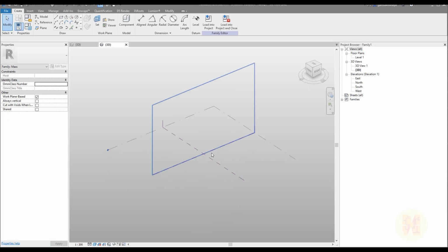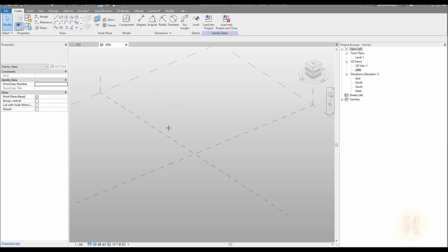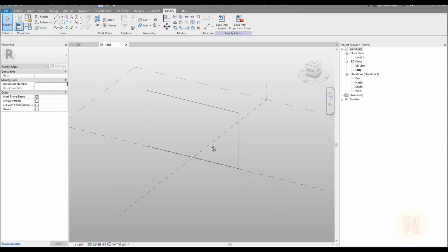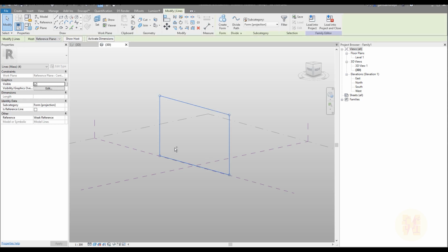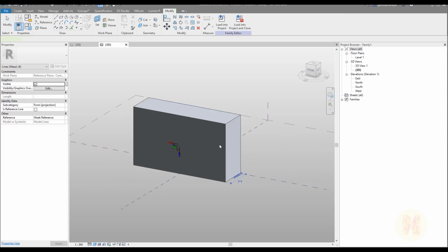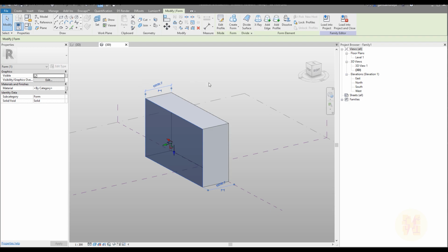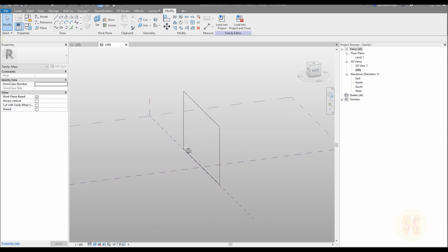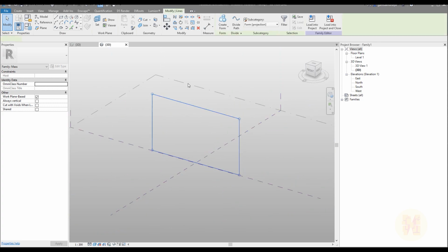Here we are. And let's create some mesh. First I will choose my working plane. Here it will be my working plane, and I will create some working plane. It's really huge, but for us it will be enough. And let's create the form. The thing is, if your conceptual mesh is created by the line, you will get straight away the form with some volume, as you can see. I will press Ctrl-Z, so I wanna end this action, and I'll select my profile.